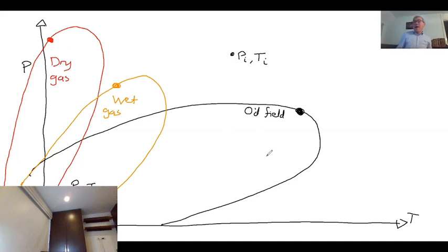And let's explain why. Right, so a dry gas is mainly methane, right? Virtually at all temperatures and pressures we're interested in, we just have a gas. If you have an oil field, here we're going to have hydrocarbons from methane all the way to C10, C20, things that are much more liquid-like. As a consequence, you're going to get a much larger oil region, okay?